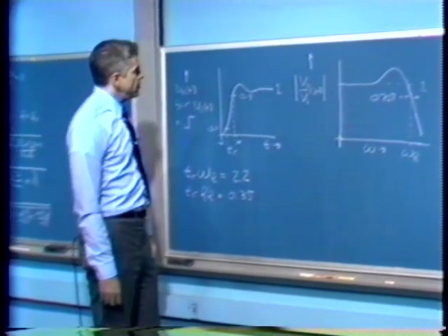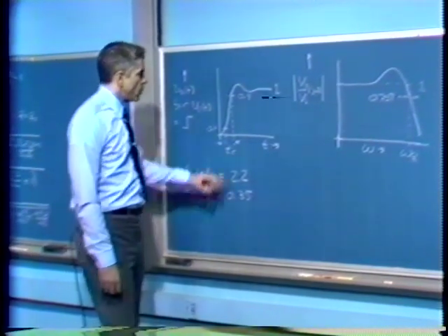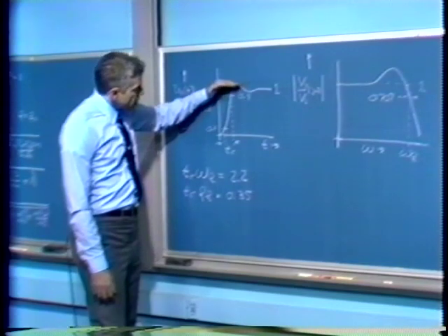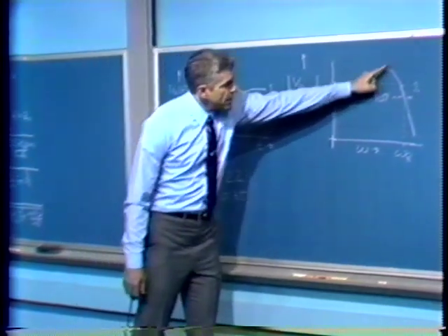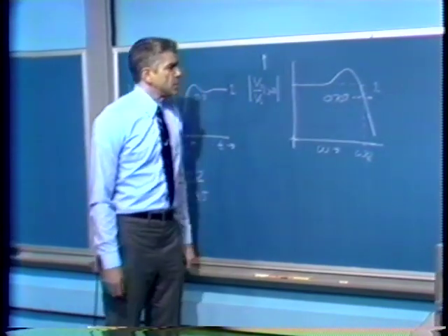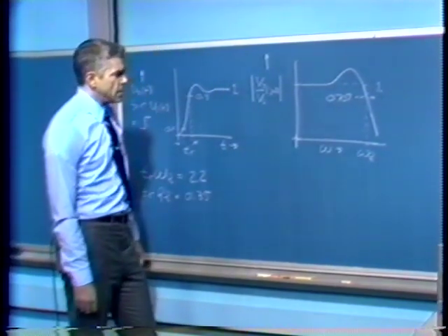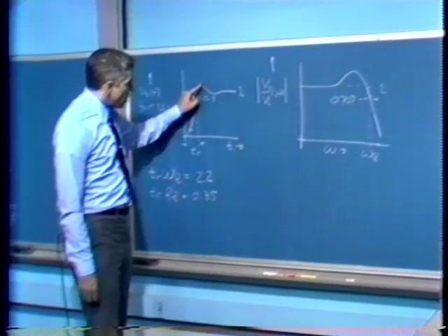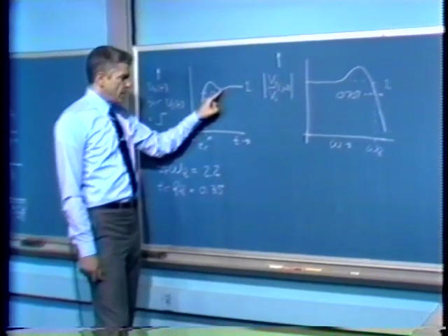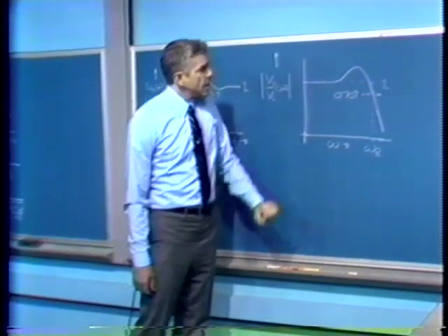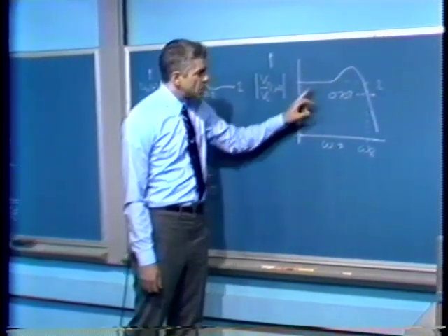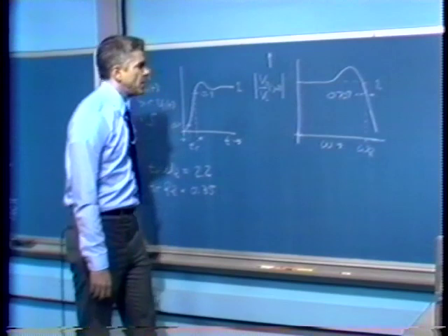And as you imagine, there are relationships that have to do, for example, with the amount of overshoot in response to a step compared to the amount of peaking that occurs in the frequency response. Those two quantities are related in some way. Larger overshoot indicates a more poorly damped system for step responses, and greater resonant peak indicates a more poorly damped system when we look at its frequency response.